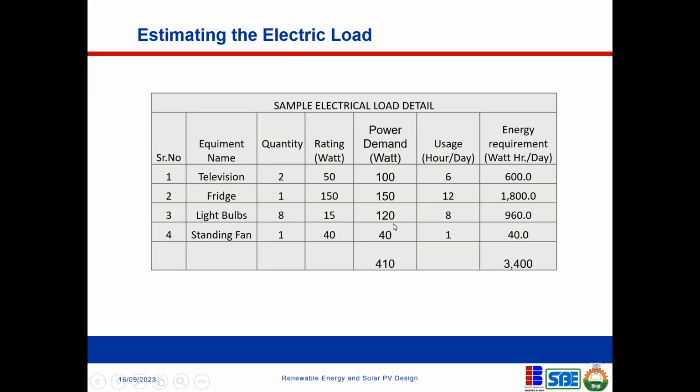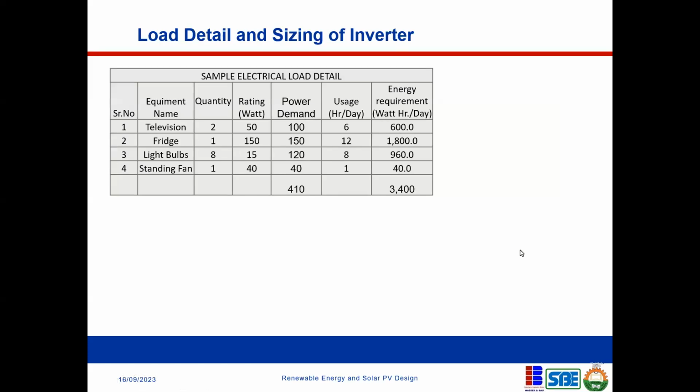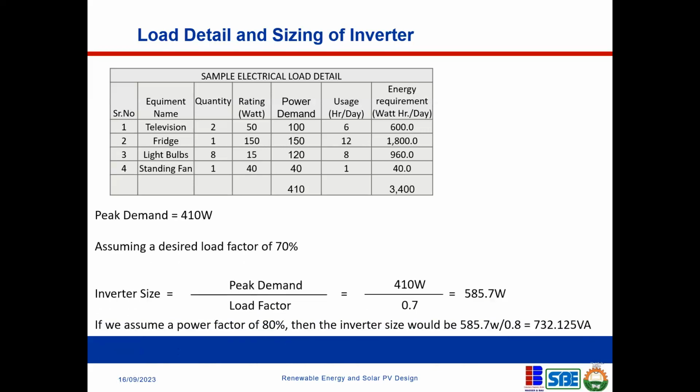So this is a sample table that you need to come up with. After discussing with your client, you need to come up with this table. Two things are very, very important: the power that the client requires, the power demand, and the energy requirement. These are two critical pieces of information that are required. Now let us size the inverter with this collected information.